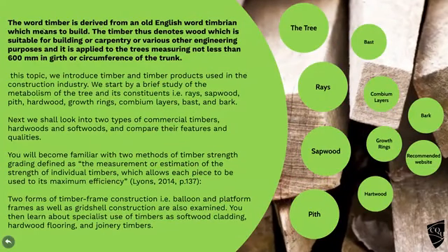An interesting pointless thing to tell you is that the word timber actually comes from an old English word, Timbrian, which means to build. And of course all original buildings were built with timber or free stone that's just lying around on the ground. So timber is basically wood that you can build with. Okay, we can engineer the stuff as well. The tree's got to be at least 600 mil in girth across, or the circumference of its trunk, otherwise it's not going to be suitable for construction purposes for various reasons we touch on later.